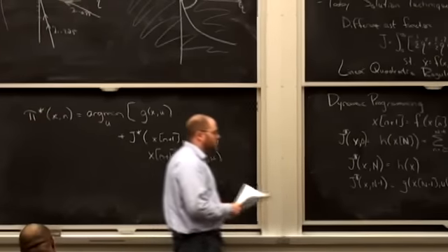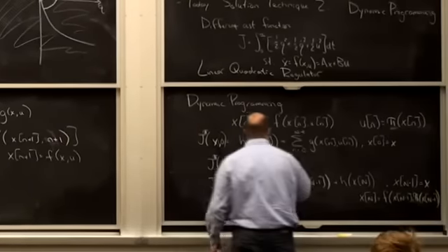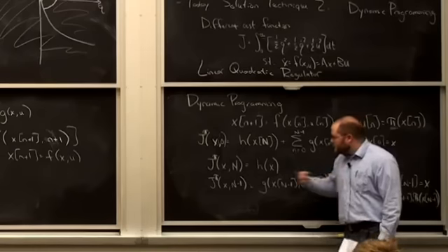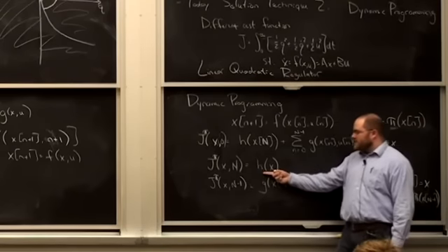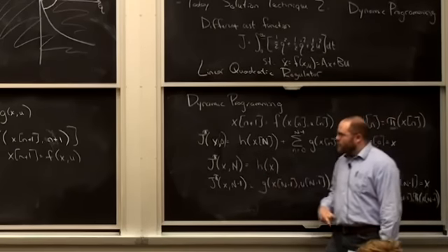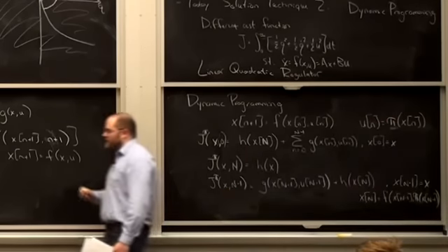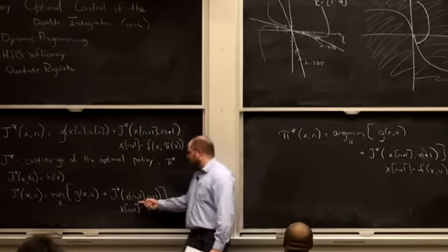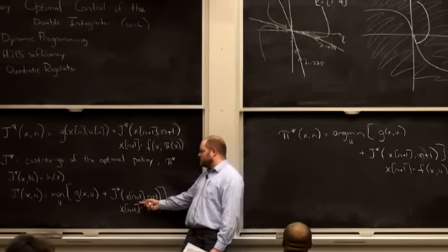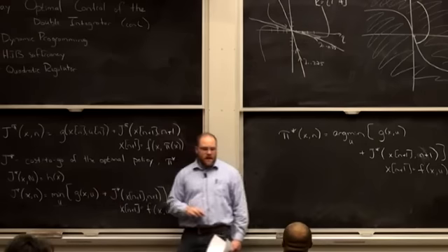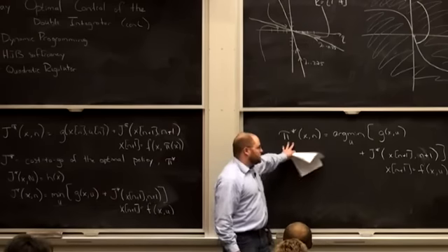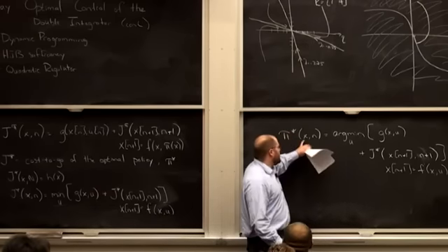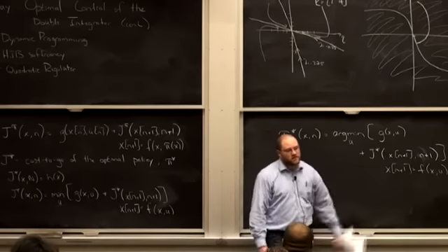So in discrete time, optimal control is trivial. If you have an additive cost function, all you have to do is figure out what your cost is at the end, and then go back one step, do the thing that in one step minimizes the cost and gets me to the lowest possible cost in the future. And if I just do that recursively backwards, I come up with the optimal policy that gets me from any x in n steps to the end.